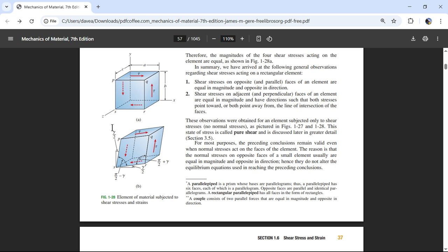And all those have to balance, and I can put them in whatever direction I want, and if I get negative numbers, I know they're acting the opposite way. Once I get those forces, those forces act over this larger area. The definition of pressure is force divided by area. So I'm going to take that normal force and divide it by A naught secant of the angle.